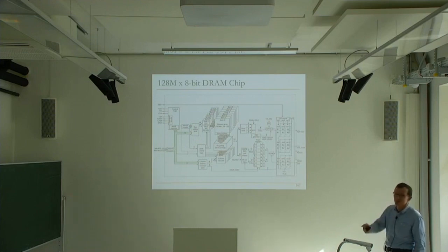The memory controller says refresh, and it waits for some time. That's specified by the DRAM standard. It's synchronous. You basically send the refresh command, and you're supposed to wait for some time before sending any command to the DRAM chip. That's why it consumes a lot of time, actually, and power. Okay, and then over here, there's a lot of mess. There's a lot of analog circuitry to ensure that the data is transferred correctly. You don't need to know about that clearly. But here, there are some interesting things.